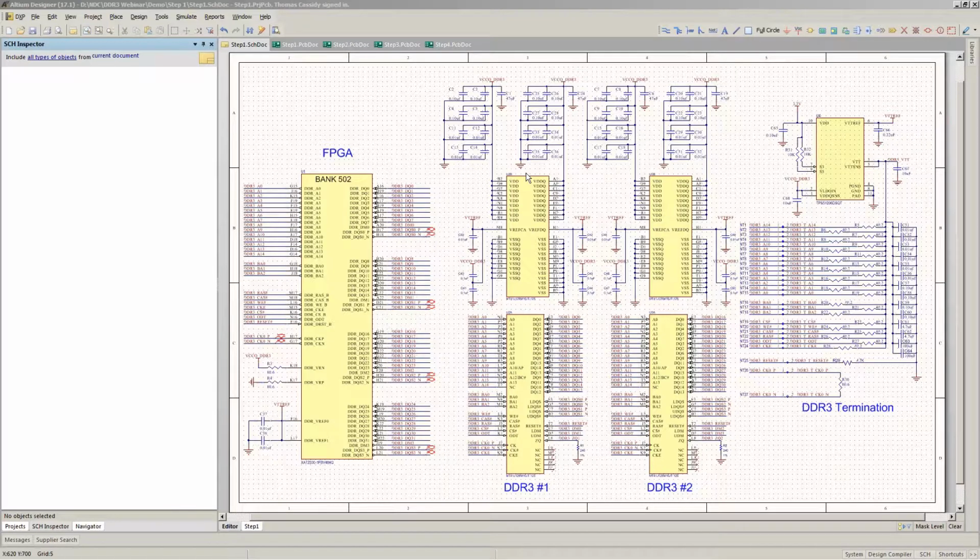As Sean mentioned, I'd like to show you a few things that typically aren't really thought of when you're doing this. One is the pin package delay. And Altium lets you incorporate this into your design. Pin package delays are basically the delay involved between getting the signal off of the actual die in the chip and getting that to the pin. If you're familiar with how chips are made, there's usually a very thin wire, or whisker wire, that connects the two. But in the larger packages nowadays, these different wires can be different lengths, and they can actually introduce a fairly significant change in your timing.